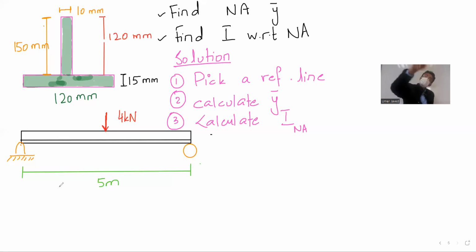So if I have to use wood as a beam, I do realize that wood is not the best choice for tensile stress. So when you put a beam that is wood, when it bends, the layers below the neutral axis will be subjected to tension, right? So I do have this thing in mind that wood is not good in tension. So I would love to have something like this. Are you getting my point?